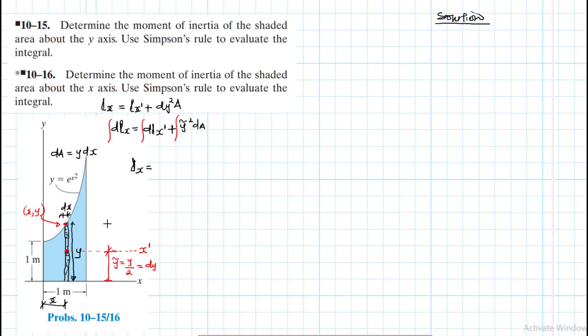the moment of inertia of a rectangle, right? What is the moment of inertia of a rectangle? Given we have a rectangle like this whose height is h and whose width is b, it is bh cubed divided by 12, right? So our b in this particular case is our dx, our h is our y, so y cubed divided by 12, then of course with an integral there, plus an integral, this y curled is just y over 2 squared, then our dA is just y dx.